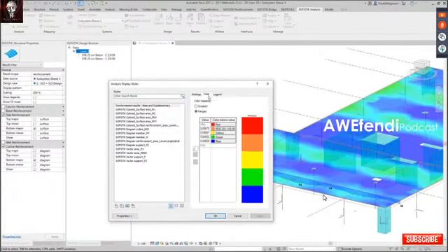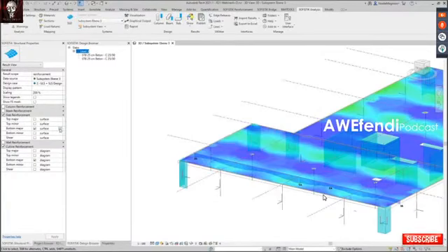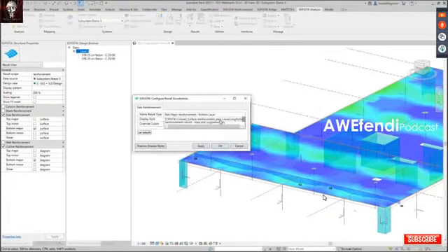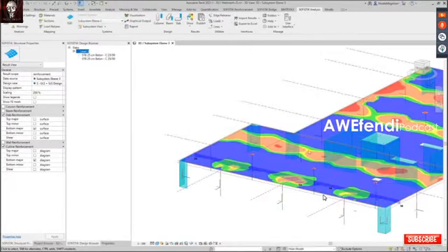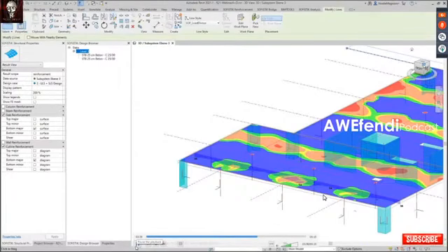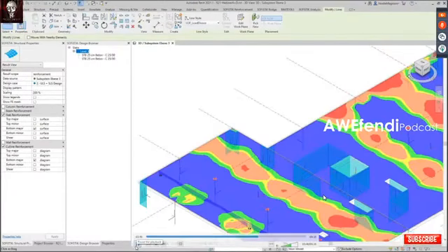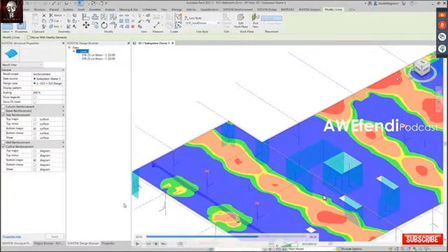For example, I have one here where I did some really rough scaling according to the different standard layers of reinforcement, so base reinforcement and supplementary layers. And I can apply it to my reinforcement result and see where I want to place my supplementary reinforcement, or where I need extra reinforcement in my slab.